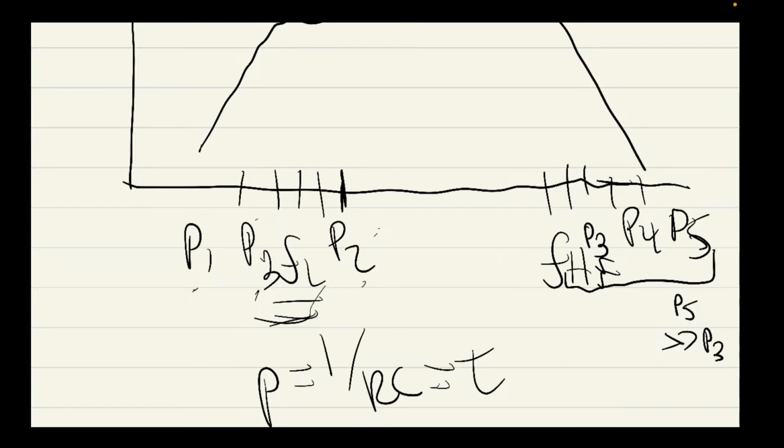So all of these poles are approximated by adding them up in series, right? And then the lower bound of FH is taken by taking these higher poles and adding them in parallel. Does that make sense? And so these poles, if you go back to what I said earlier, are your coupling ones, your low frequency ones, and these are your high frequency ones, your shunting.